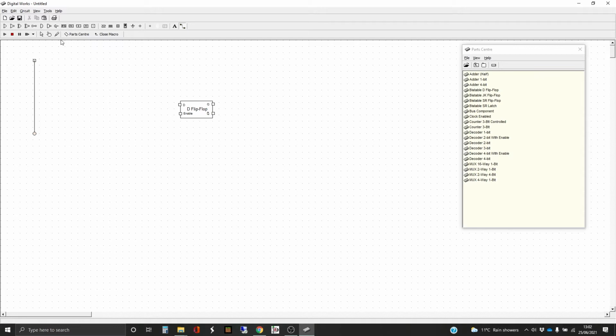And in the last video, we discussed the fact that in order to take our output to the bus, we need to use a tri-state buffer, which is a special component which disconnects most of the time and only connects when you use the enable line that's underneath. So we're going to have the enable in here, and we're going to feed that out to the bus.